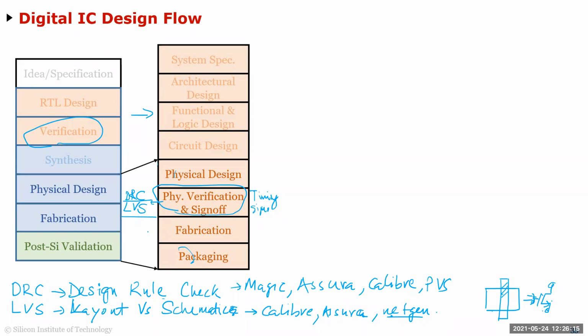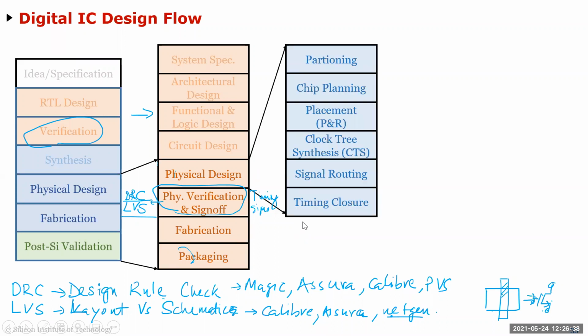So you'll get a report with, let's say, 10,000 errors, and you'll go in and say, okay, this error came because there was a setup timing violation in this path. So I can put a buffer and fix it. This the designer needs to fix. This we can probably waive. So you cannot do this without having full knowledge of timing, like STA, timing data, and so on. Okay. So that's the extra time.